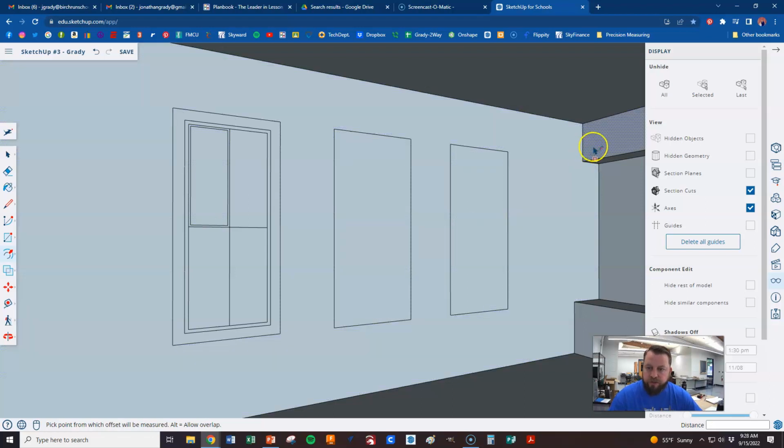And just like I showed you guys on this one up here, where with the push-pull tool I could just double-click it and it remembered my previous push-pull, the same thing happens with the offset. It actually has a memory and it remembers my last offset. So now I'm going to double-click this pane, and it automatically offsets a 1/2 inch. Double-click and double-click. And did all of these panes just the way that I would like them to.